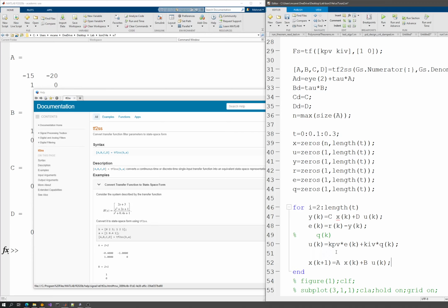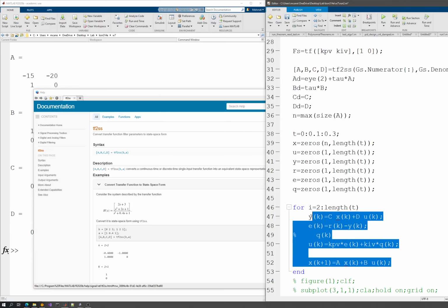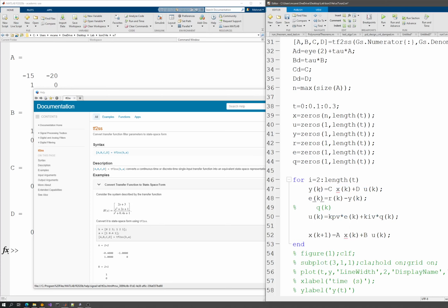And if I have the integral, I will go ahead and calculate the control signal. Once I have the control signal, my first state or my first time instance value using the initial values will be constructed. At this point, I will use xk plus 1. Now, if I have done this one here, my k will be increased automatically because I'm using a for loop. It will then give me yk plus 1, but I will denote it with k because it will be the previous value at that time instance. So then this will start over. So this is basically how the code will look like somehow, and I need to change it a little bit.